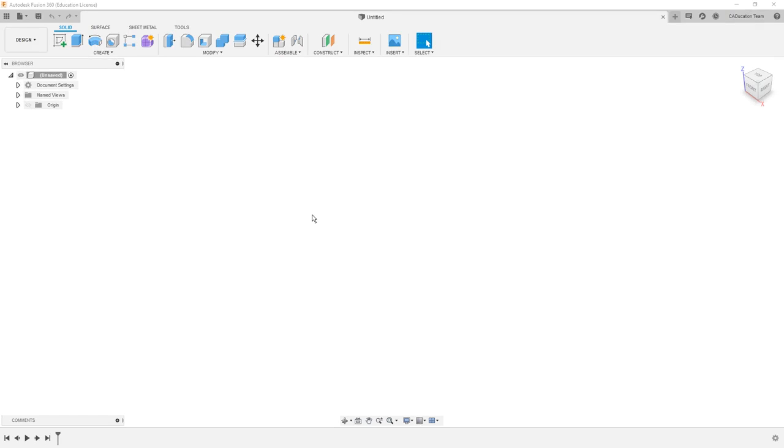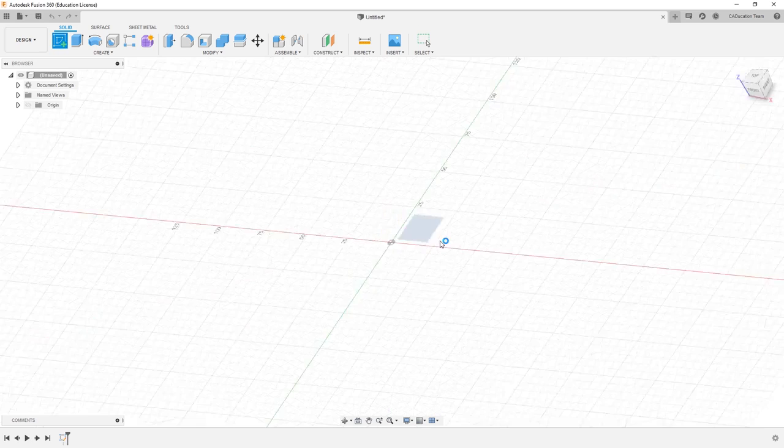For this next lesson, we're going to start with a new untitled design. We're going to create a basic box, and we're going to convert a face to modify as a form. We've taken a brief look at this in our first lesson where we talked about the differences between a BREP and a form. But we want to start from scratch by creating a sketch, select a plane,